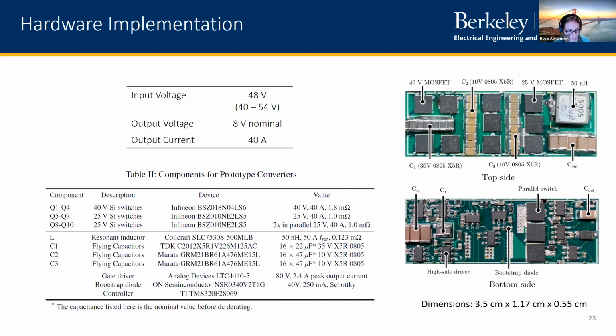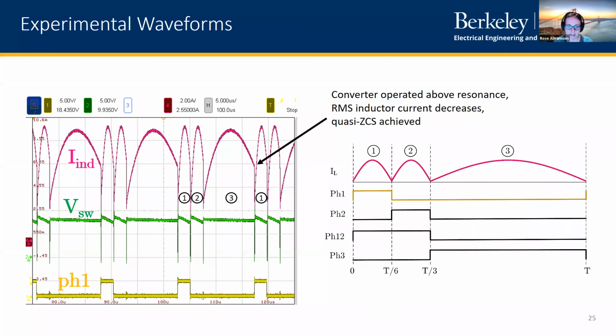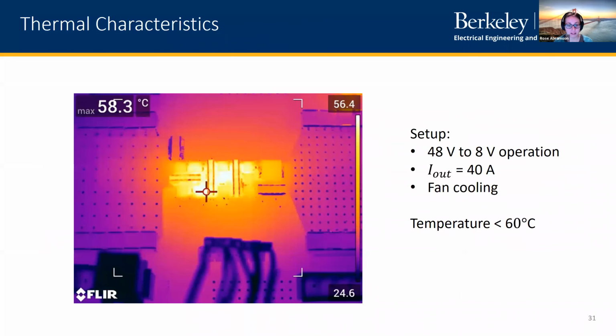So we have a larger board so that we can have connectors connecting to the power supplies and the efficiency measurement sensors. And so we do have a larger ground plane for that whole PCB. But if you look at the thermal image, you can see here, the hottest part is that bounded box power conversion stage.